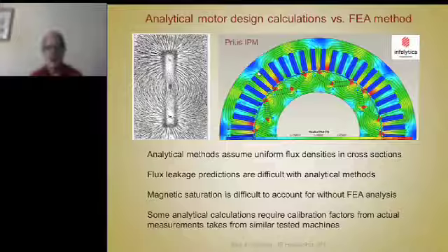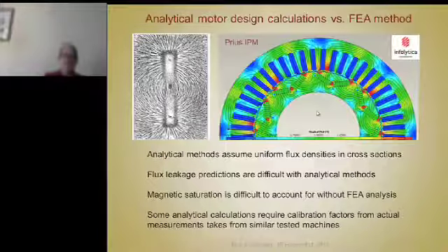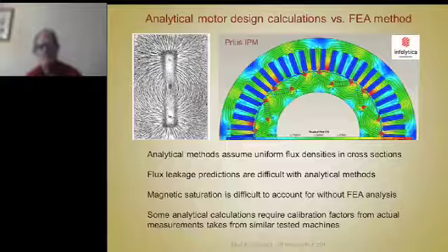So you can go to a higher order FEA solution, which just increases the number of elements, and that smooths up these equal potential lines. It didn't really change the torque or the final result all that much, but it sure makes you think it does. It looks more uniform, and it certainly looks better in your report. Although having said that, you still can get some errors through too coarse of a mesh. A mesh is the picture of all the elements that you pick.